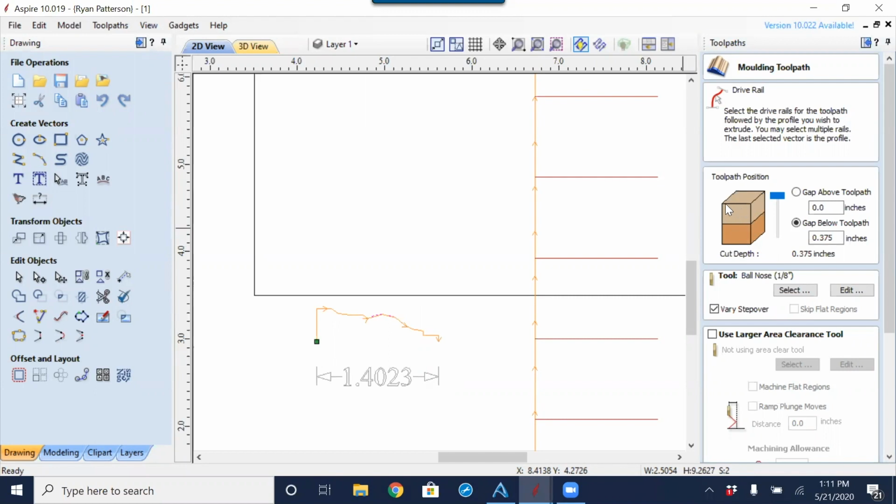So this lighter brown section here is the height, and it is the area of our material that the profile is going to be cut through. We could change that and bring that down or bring that up. Typically, you probably want to have it sit down in from the top of the material just a little bit. And once we preview what these two settings look like, where this sits, I'll come back to explain why you might have it down a little bit or farther down or different like that.